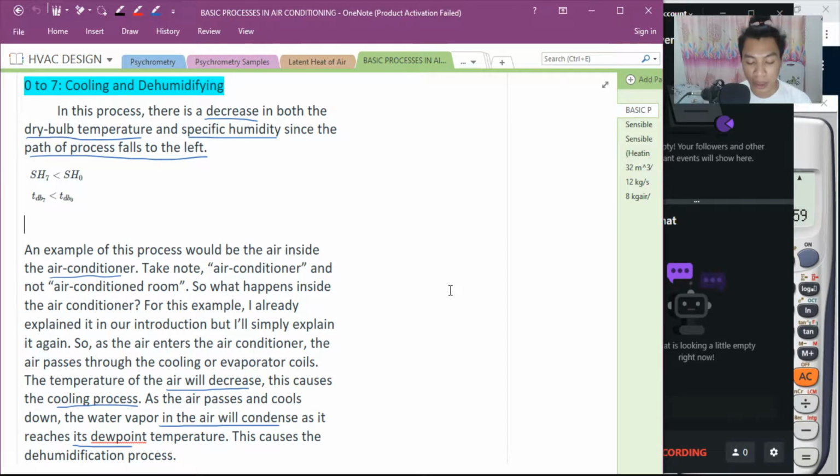And then, when cooling coils are used, the temperature of the film of air in contact with the surface of the metal pipings, the chilled water system supply, determines the condition of the air flowing through the coil. The temperature of the surface film is always at some point between the temperature of the air and the temperature of the water, so they reach thermal equilibrium between the two. Or often, the refrigerant inside of the coil. So, the refrigeration system may be involved.